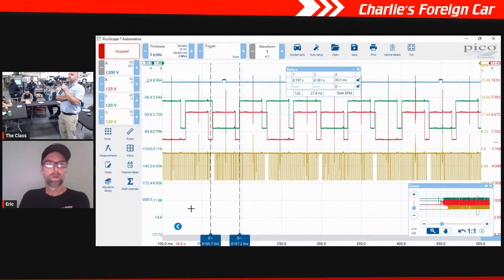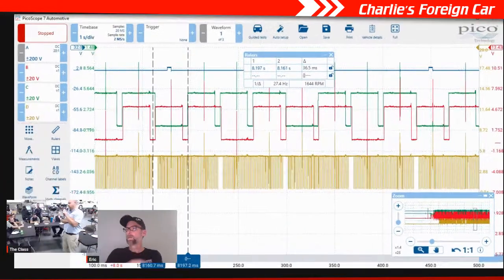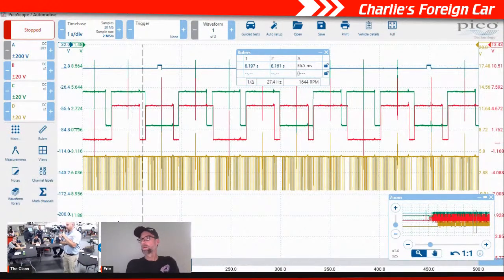So the DME sent the signal all the way up to the valve. And then when we did it on the intake, it was weird. They were both B plus signals, but one of them had this funky, almost like a signal, going from power to ground really fast.